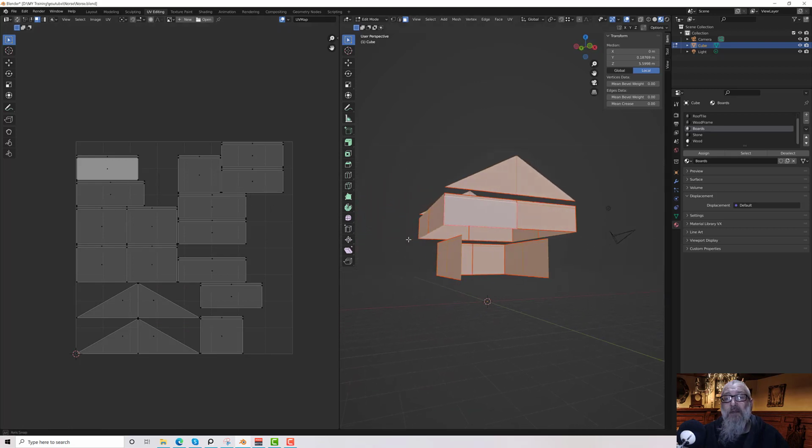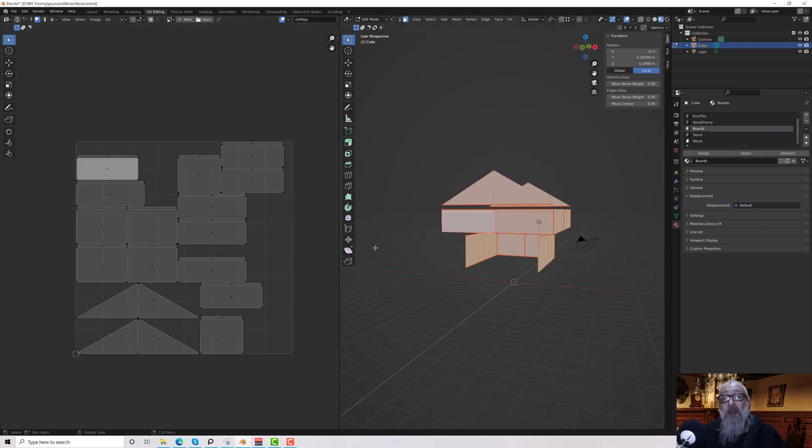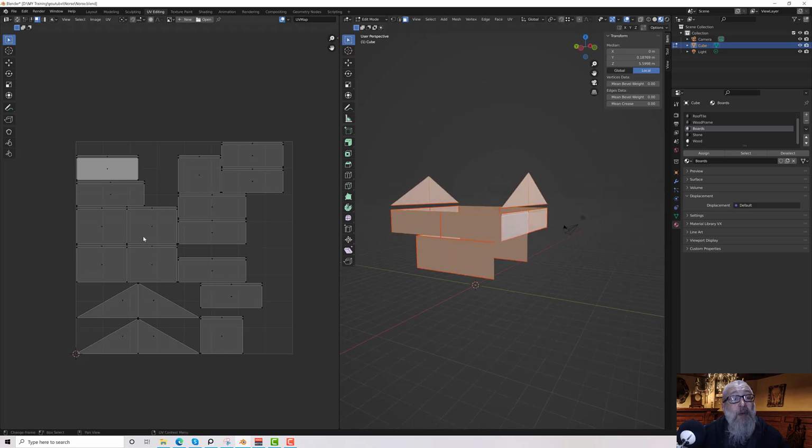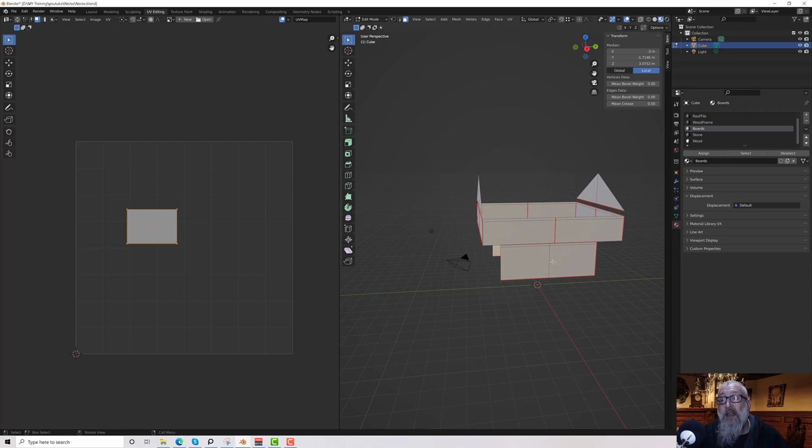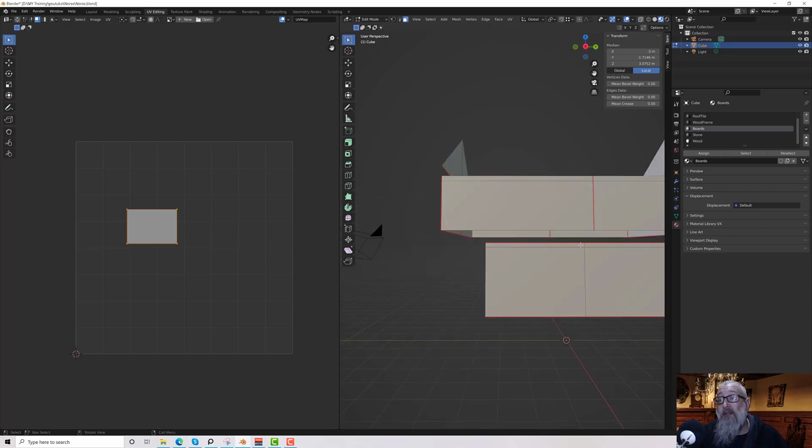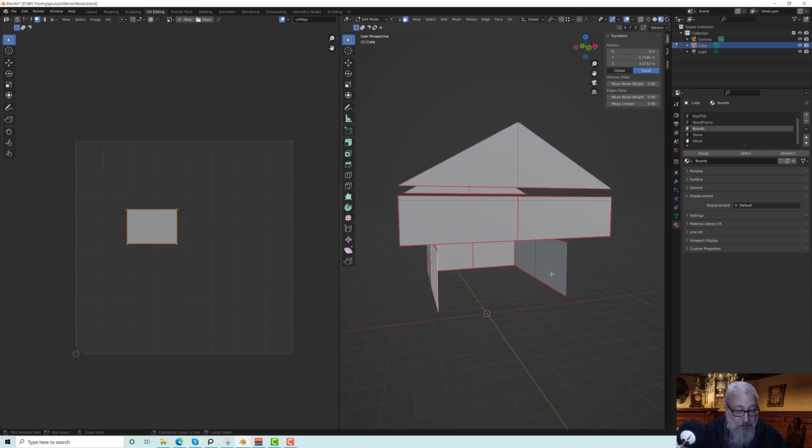There we go. So we've got slightly more definition now. We've got slightly more, can I put it, UV space to work in, because we don't have those huge long islands. It's working a little bit better, and we could do the same for these bottom ones, but just note that if you do that, you'll need to model something in here to hide that island.